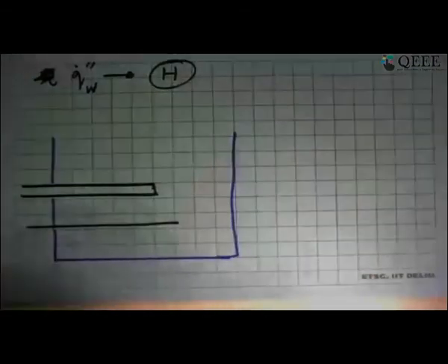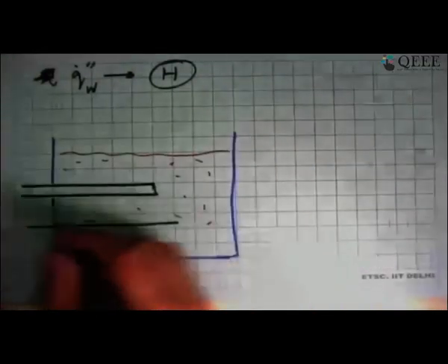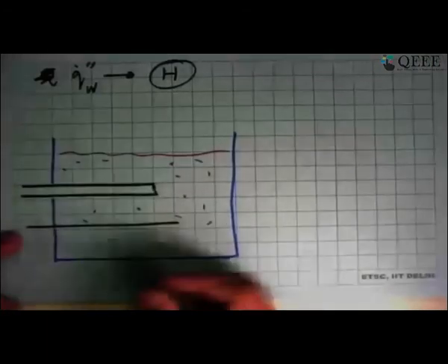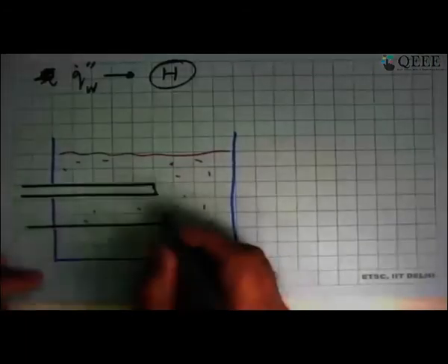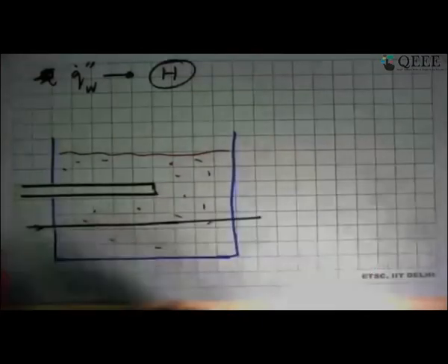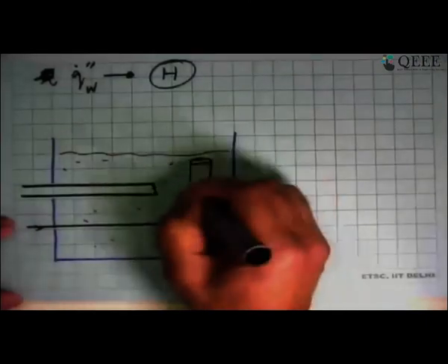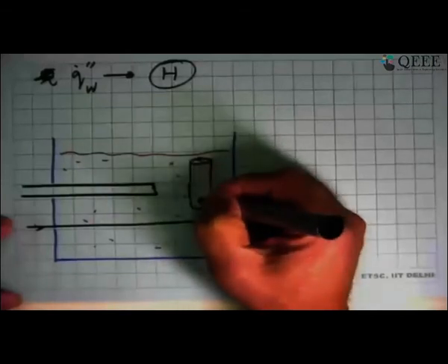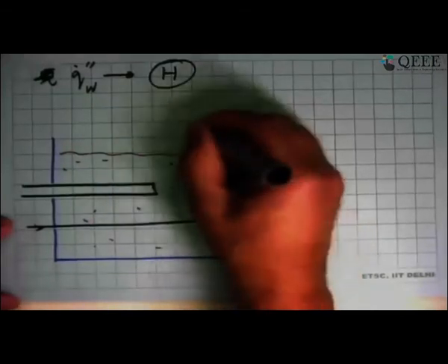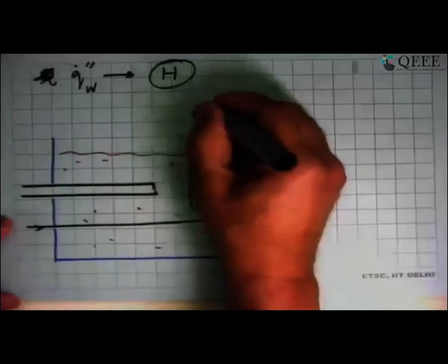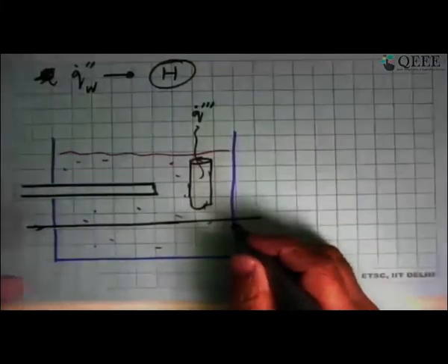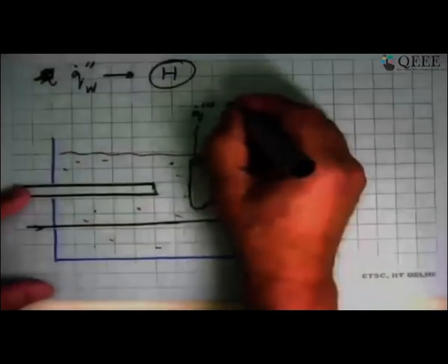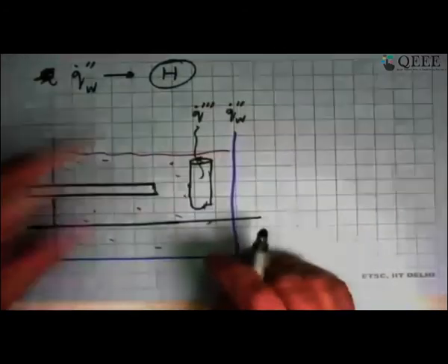That's the pool there, and this is the saturated fluid over there, and this is electrically heated. So this wire need not even be like this, but we could take this wire through and through and pass a current through this. Or another example is a nuclear fuel rod from a nuclear power plant. Here the reactions are generating heat. So the boundary condition that we have in this case is a volumetric generation rate of a certain amount, and so the surface sees Q dot double prime wall as a constant. So this is an H case.